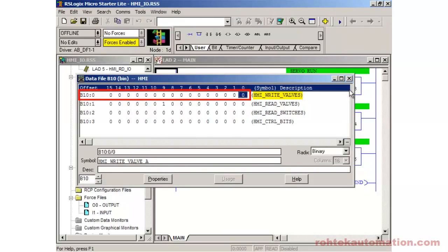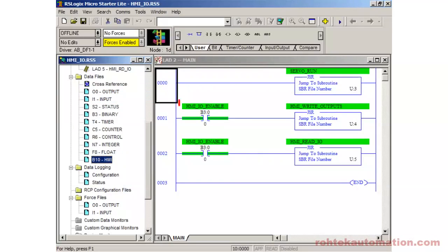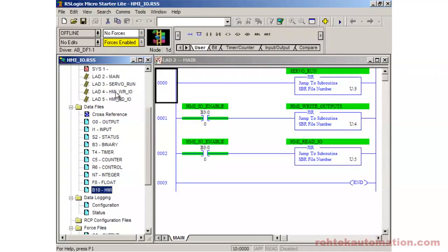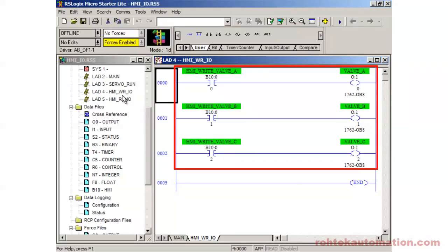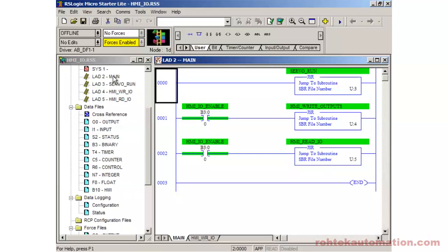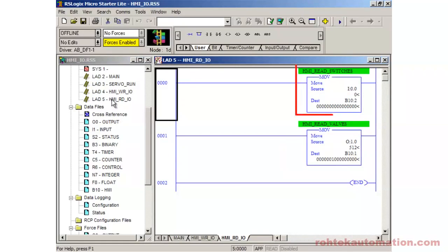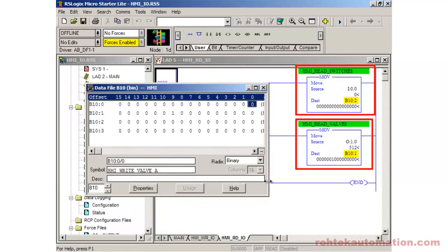If the running PLC program has enabled HMI control, then a simple subroutine copies the bits from the HMI interface table to the outputs every scan. In this case, we've copied bit by bit because we like to be very explicit when allowing HMI control of outputs. In servicing the HMI reads of I/O, we just move or copy entire words of input and output bits to the interface table for HMI access.